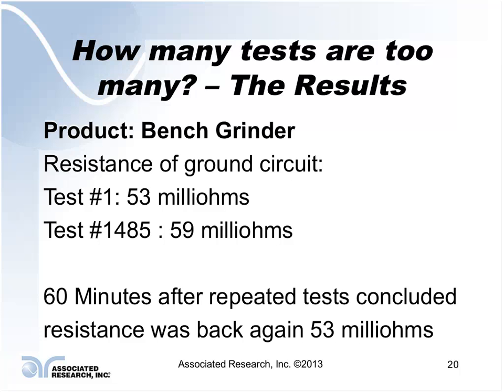Probably wouldn't have taken that long, but we happened to think about this about an hour later. Well, let's go back and retest it again to see if there's any change. Apparently, just going through all the repeated testing, there was enough heating of the ground circuit, pumping 25 amps of current through it for 5 seconds, off for 1 second, doing a Hipot, and then energizing it again, where the resistance did increase slightly, but once it cooled down, it dropped back down to the original readings.